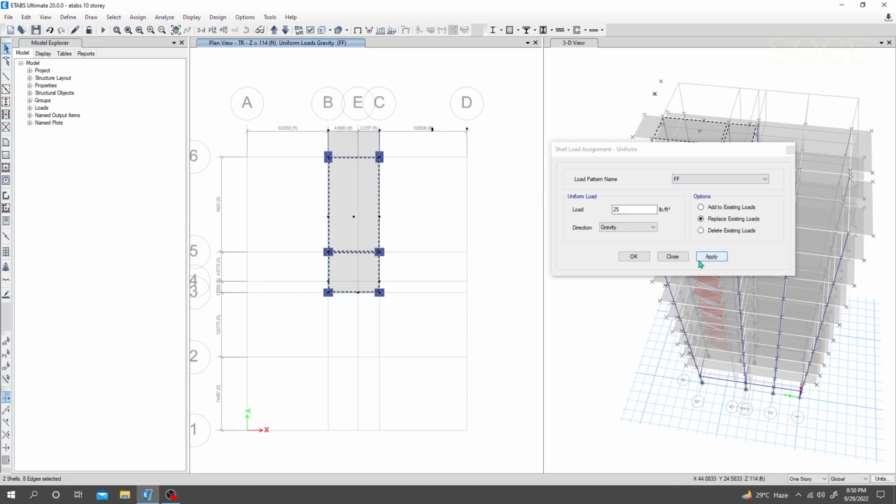Also we'll provide a floor finish of 25. It's done. Then roof live load pre-select. Okay, floor finish also will be here, so 25 floor finish, replace. It's done. Then pre-select from here roof live load, that will be, suppose consider, 40 or 60.